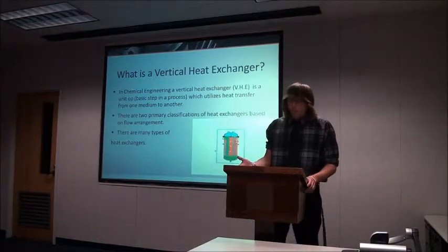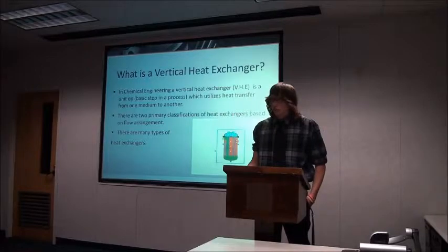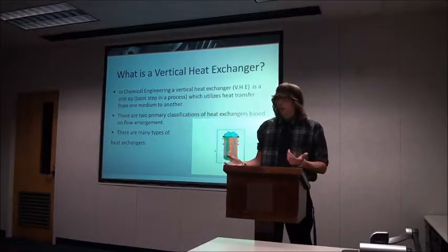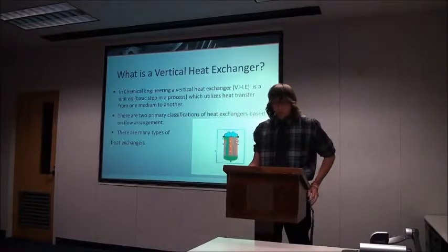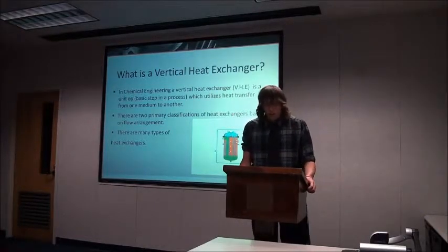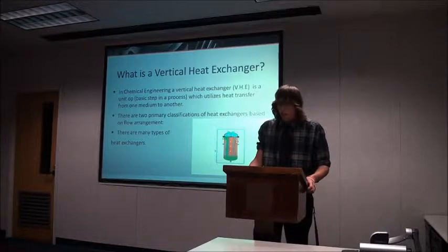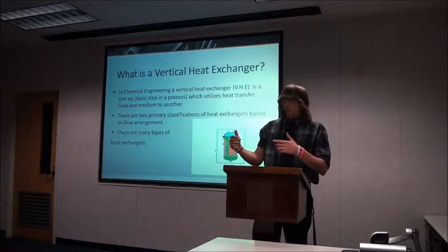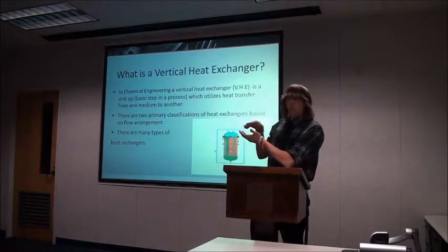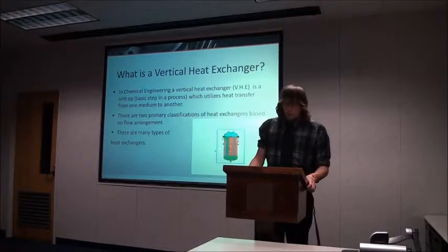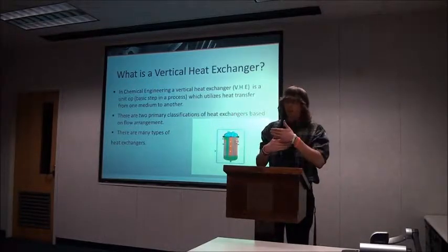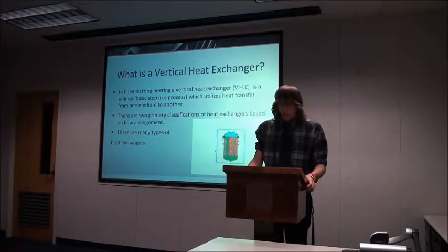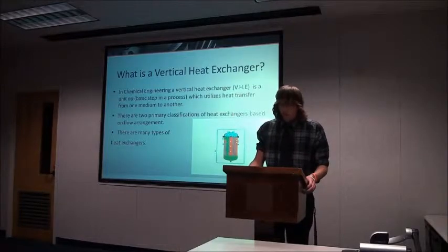There are two primary classifications of heat exchangers based on flow arrangement. You have parallel or concurrent flow, or countercurrent flow. In concurrent flow, the fluids enter the exchanger from the same end and travel in a parallel, similar direction. While in countercurrent flow, fluids enter the exchanger from opposite ends and travel in opposite directions, transferring heat to one another.